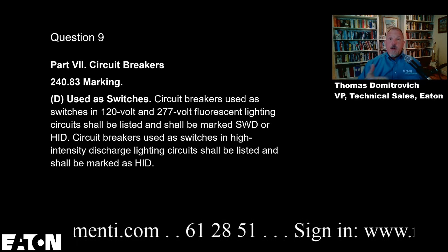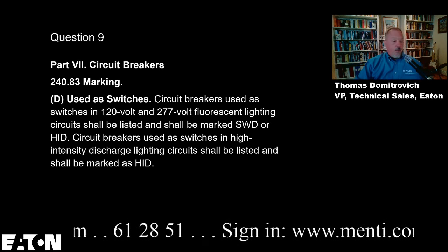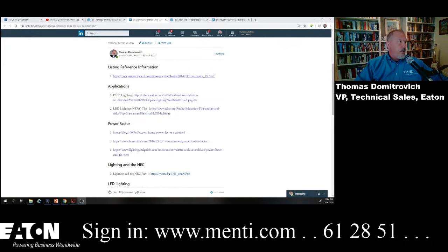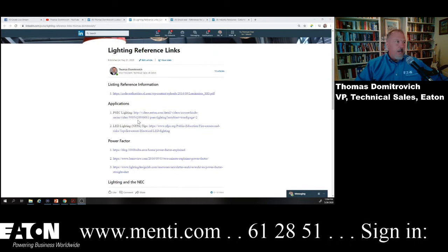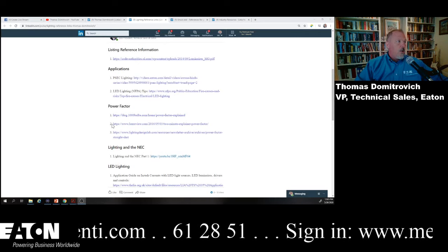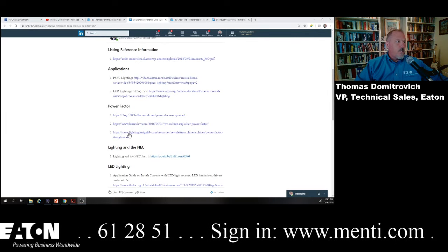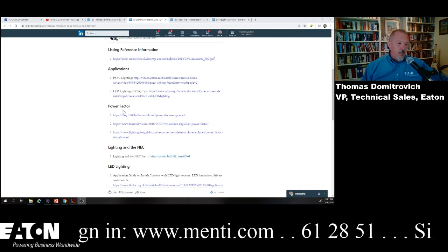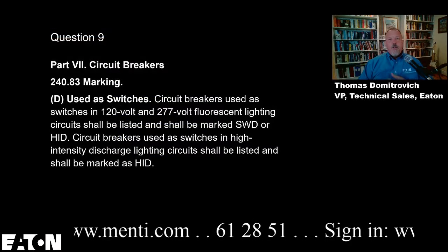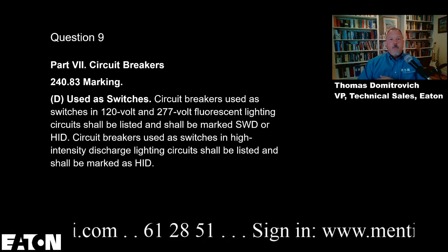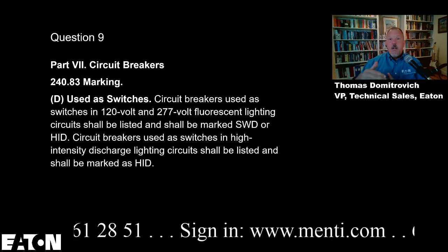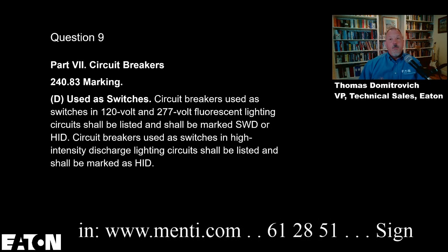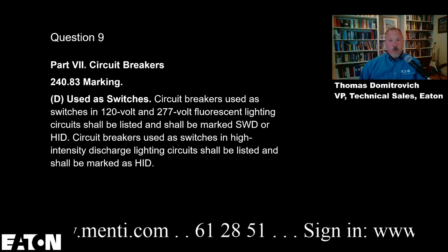We had a discussion around power factor as well. I put the references on my LinkedIn article. I've got 3 different blogs and 3 different references, just industry chatter around this topic of lighting and power factor. But we test our breakers to switch these lights at a different power factor than we would others, and we do more cycles.